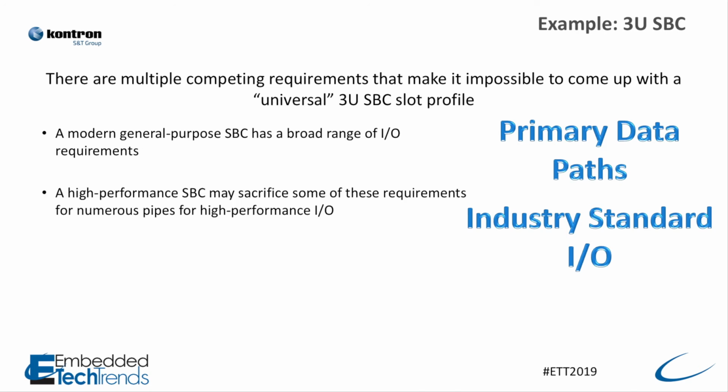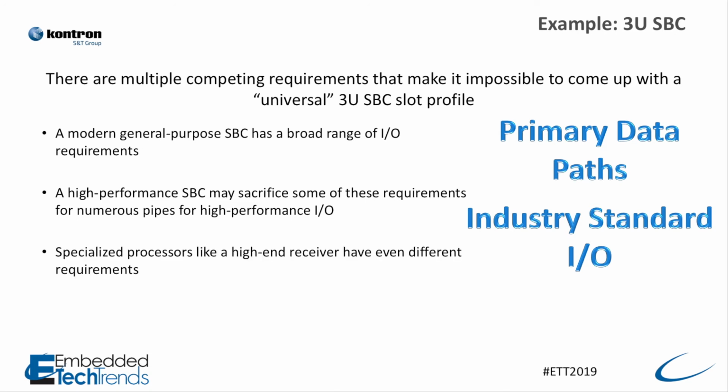But then there's high performance SBCs. You have an FPGA-based SBC. You don't need all of that USB and 1000BASE-T stuff. You just want fat pipes in and fat pipes out. You have specialized processors like receiver cards. Well, there's no reason why they couldn't use the same kind of slot profiles, but they have different needs. They have RF they have to bring in, or optical connections you have to bring in.